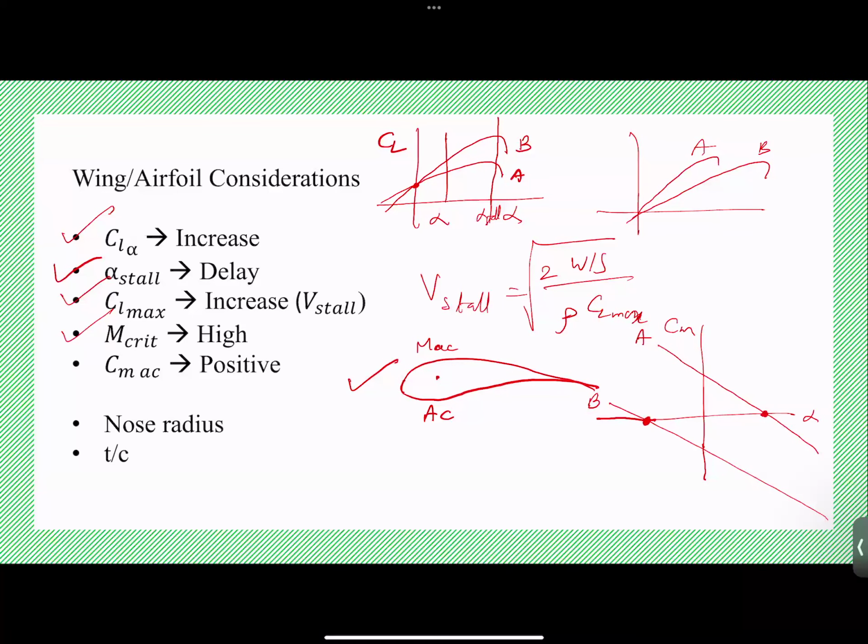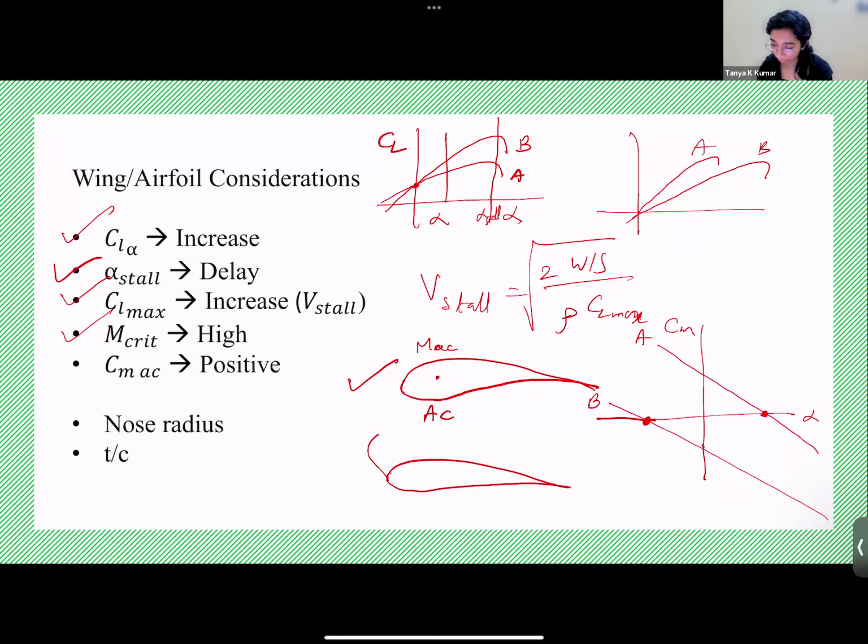The initial pressure distribution over there. Okay, so pressure distribution. Let's just discuss that. So you have something like this, and you have something like this, right? So it has this pressure distribution, and it amounts to a difference in the forces, which gives you a net lift. So there is a net lift and net drag. These are the net aerodynamic forces that are caused due to the pressure differences, correct? So this lift and drag, they're considered to act at which point?